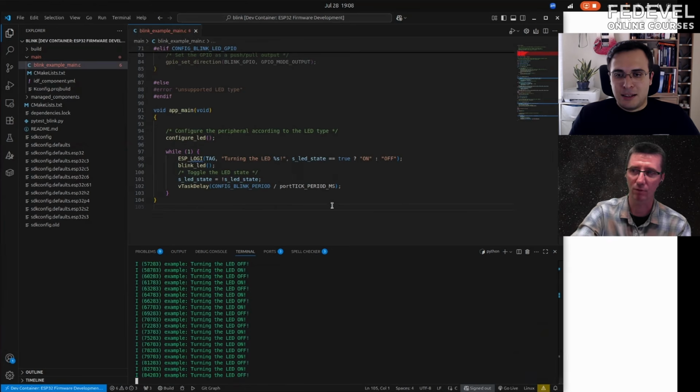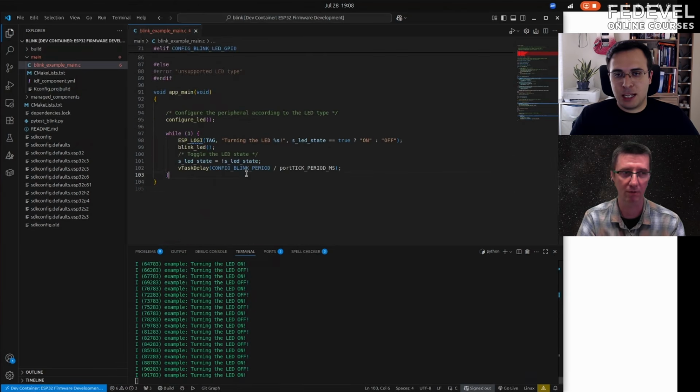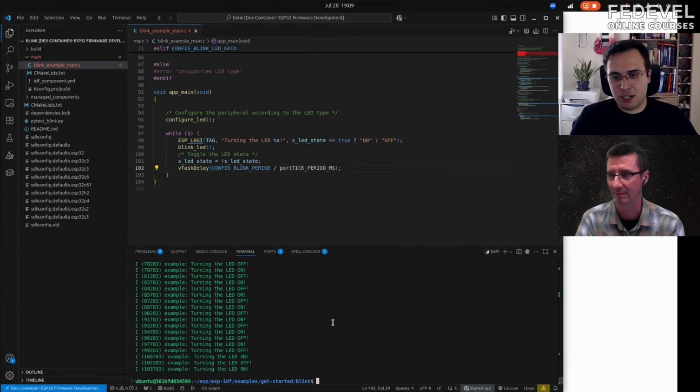Now if you would like to change something, we can change it directly in this code, for example change the frequency, or we can also go through the frequency setup again and change it, depending on what you want to change. Here the frequency, for example, we change it from a configuration, but I don't need to choose a configuration here. You can just write it, for example, change it to 500 milliseconds, because then it will be more visible. Yeah, it blinks faster.